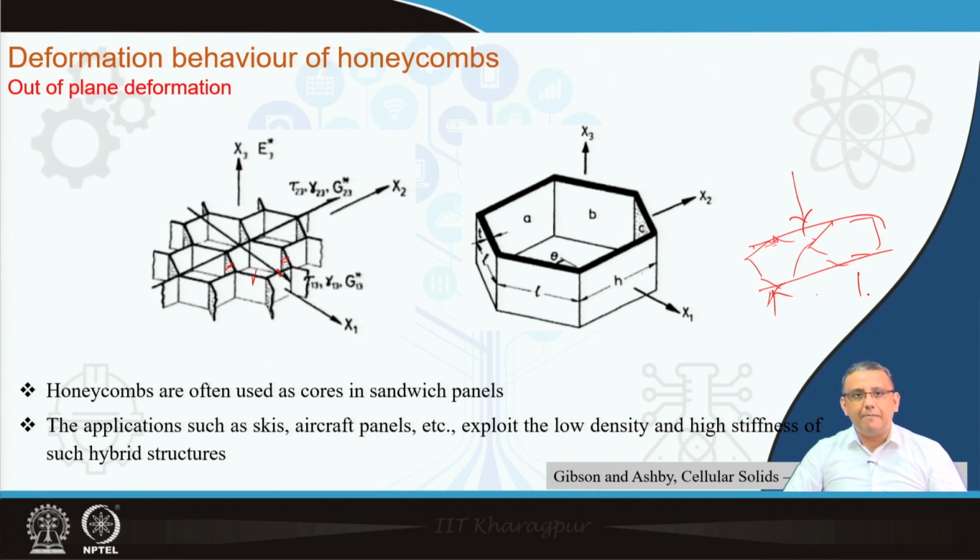So, this was all about the deformation behavior of honeycombs. We learned several aspects, and next we will discuss the deformation behavior of foams. There we will differentiate between open cell foams and closed cell foams, and also, as we did for the honeycombs, between different material behaviors like elastic material or elastic-plastic material, and also ceramic materials, which are brittle materials.